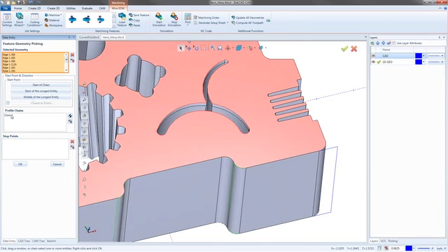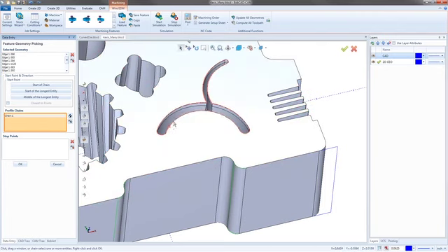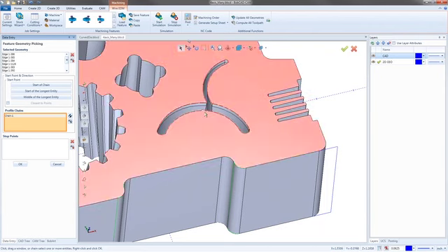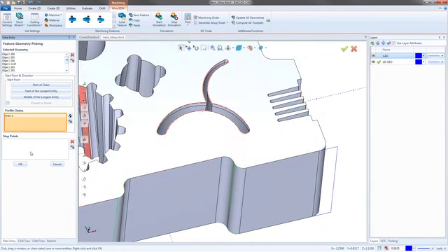We could also come in and click on the chain here and actually pick by clicking where we actually want this thing to start. So we can click where we want and also look at our direction here so we know which direction we should be compensating in. I like to do it just because it's easier to figure out now what comp I may be using, even though 2-axis inside will figure it out and it will change it.